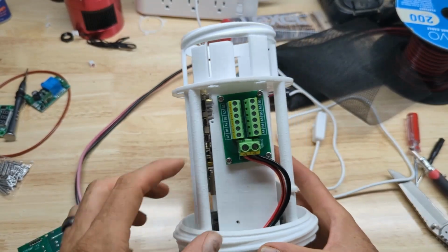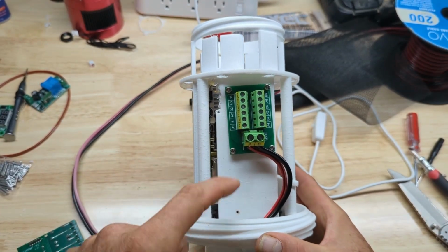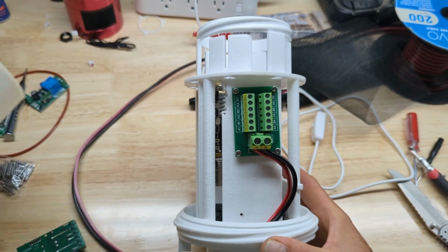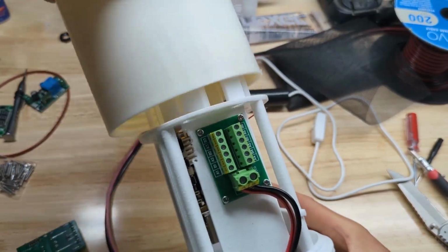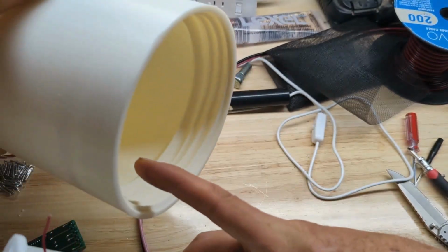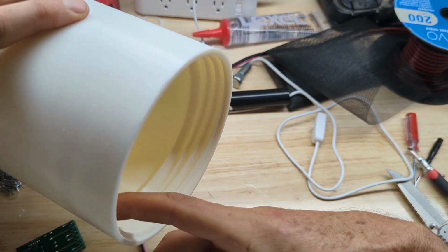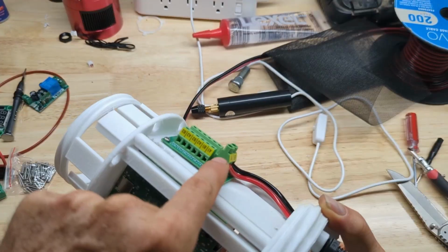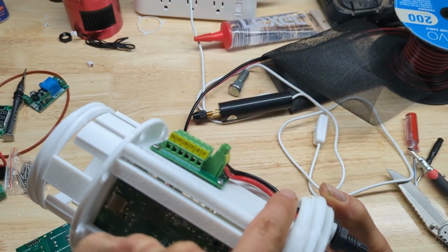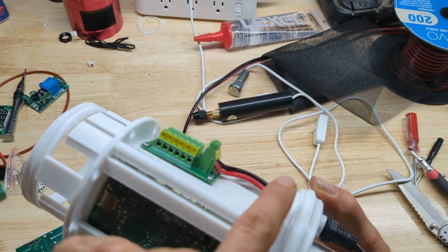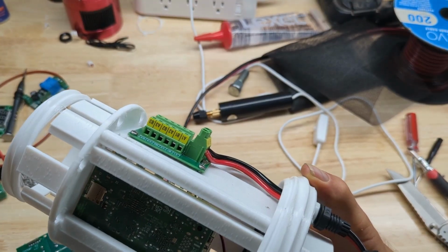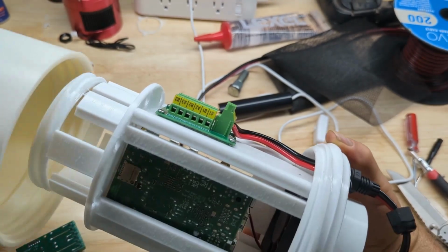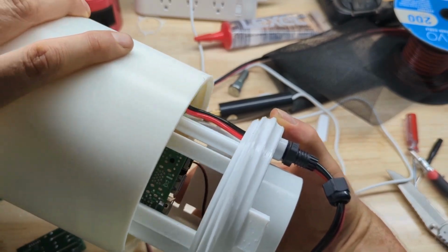Okay, so I got this power distribution block mounted. I was going to mount it down low, but when I actually put it down there and did a dry fit of putting this cradle into the tube, there's a ridge on the bottom of this tube where the O-ring sits, and that was just too close to where these things protrude out. So when it was down here, it was interfering with that O-ring ridge. So I've decided to move it up, and this way it's got plenty of clearance up here in this area where the tube is much wider, so you see it easily passes that.